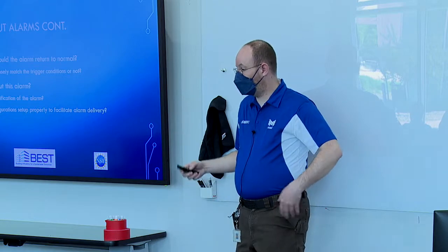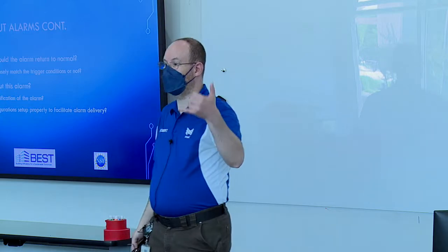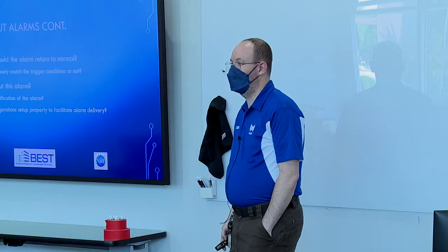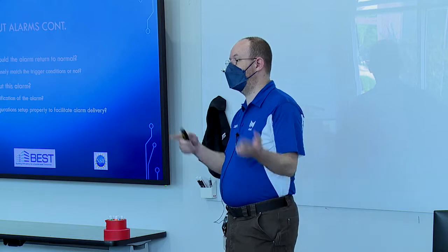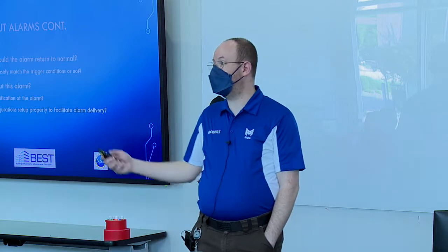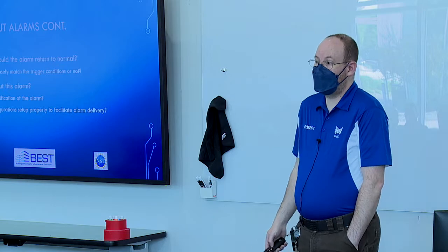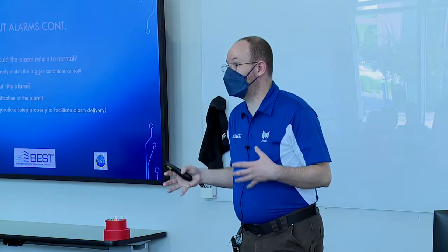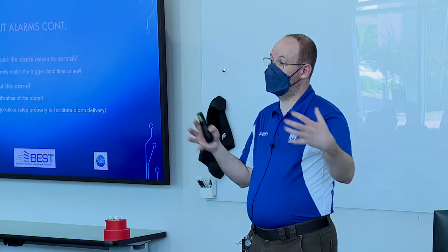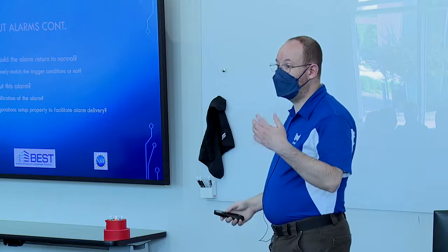And this also comes back to those priorities. Are we telling the manager about every alarm? Or are we just telling the on-duty phone about every alarm? Are we notifying the manager about alarms at all? Does the manager care about the alarms, or is it just annoying? I've got people to deal with this. Why do I keep hearing about it? Because if the manager's job isn't to deal with dispatching and making sure those alarms get dealt with, then every alarm to them is a nuisance alarm because they've got bigger fish to fry.